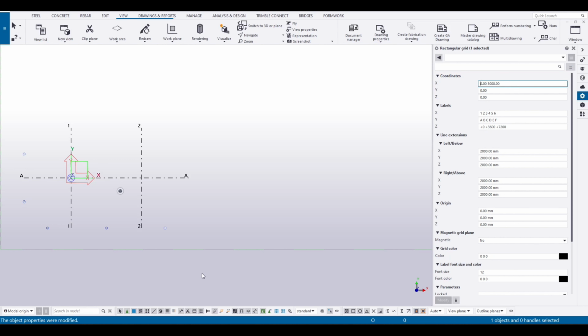And I have a new grid line, the second one, which is separated by 3,000. It's at 3,000 from the origin, right? So it's at 3,000 from 0. If I want to add another grid line, at 3,000, it's going to be at 3,000 from the 3,000 here. It's not from 0. So one grid line and the other grid line are separated by 3,000, and another grid line here. But to remove the confusion, I'm just going to remove that and make 3,000 again, right?